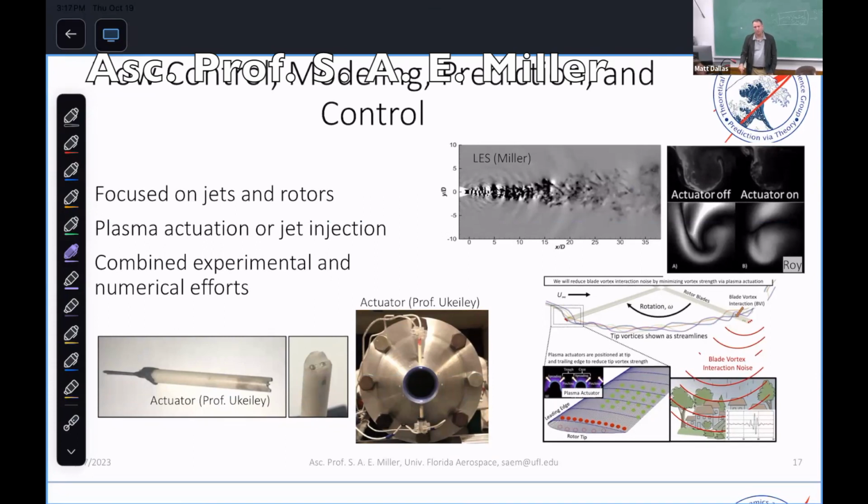So we design control algorithms, which are just math algorithms, which drive plasma actuators to control turbulent flow. And you might want to do that on jet nozzles to do thrust vectoring or maneuvers without having moving surfaces. This is the kind of stuff that's been used in the Israeli Air Force.